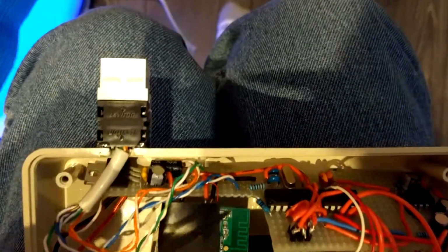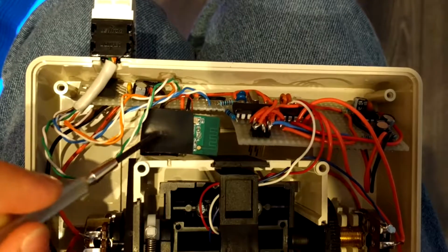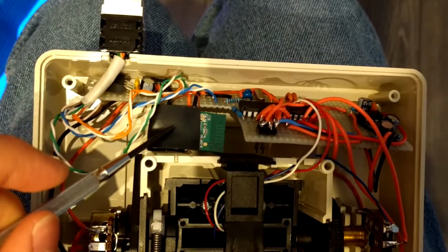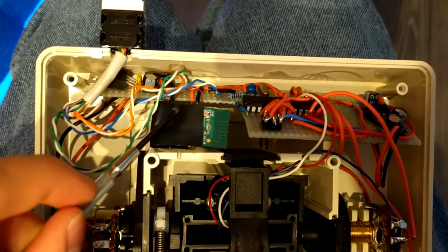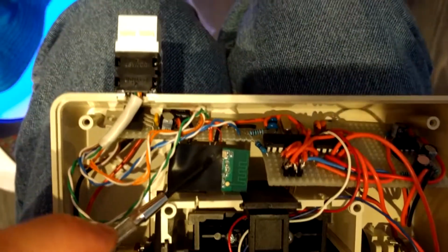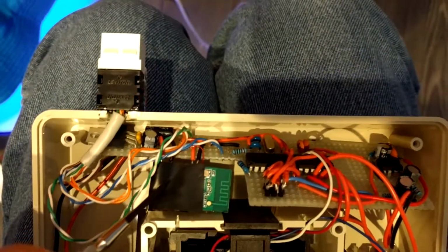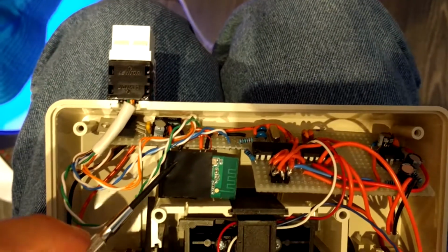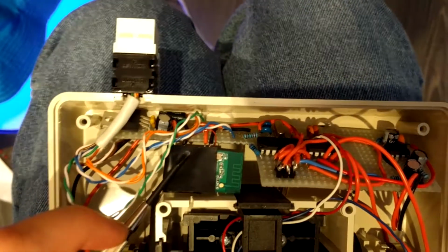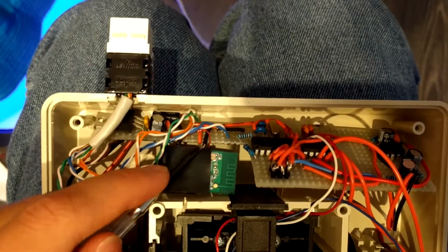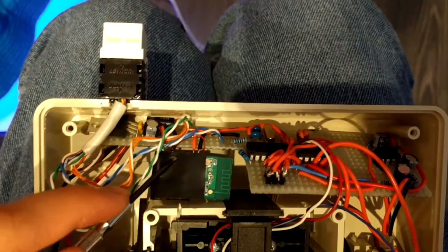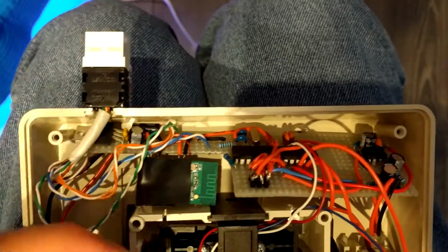And then I have this OVC3860 Bluetooth module that I would not recommend using because it's terrible, but I used it for this project just to try it out. All you really have to do is add power to it, and it does everything by itself, unless you wanted to do some other serial commands with it.